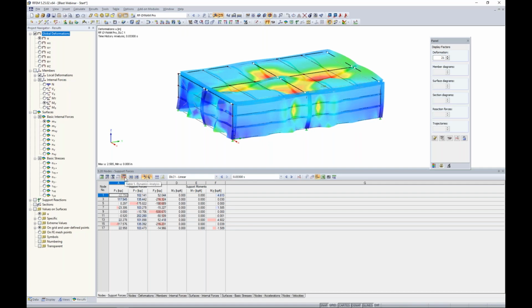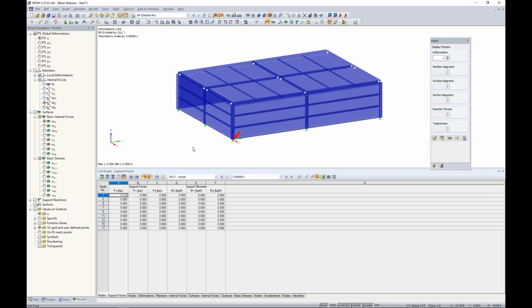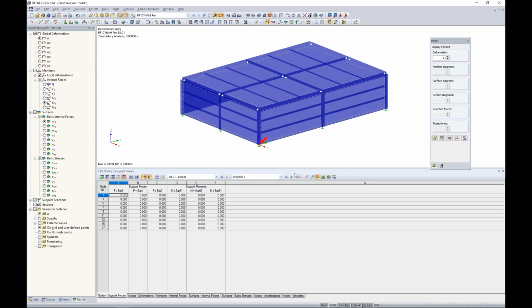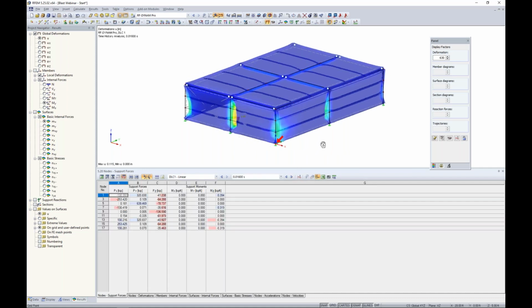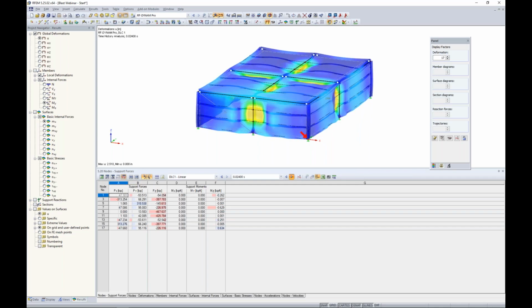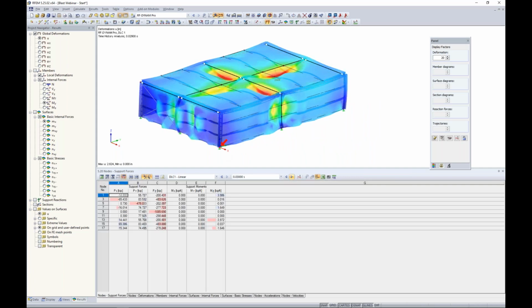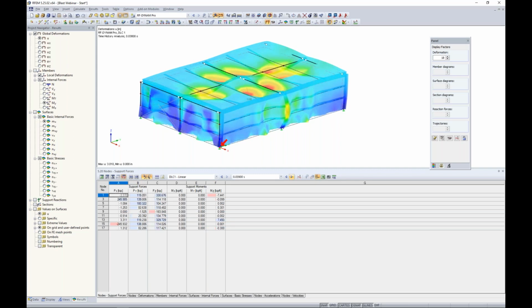We go to table 5 here. Under my dropdown, I have my natural vibration case, but now we have our dynamic load case as well. Right next to that is going to be all of our saved time steps. So if we're looking currently at the global deformation here, and we have time step 0, well, we can actually scroll through these, and remember, nothing's happening on our structure here until we have that estimated time of arrival at about 0.016 seconds. And that's where we start to see this blast load impact our structure. And we continue scrolling through these different time steps to slowly see that wave load travel from the front of the structure to the center and the roof and clear back to the rear of the structure.